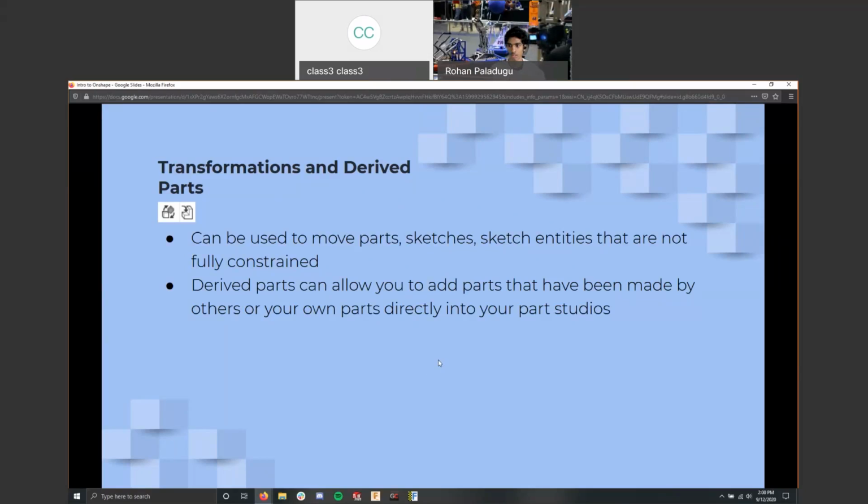Some teams, like ours, tend to just do the math based on our calculations, and then in the assembly we just place whatever part we need accordingly where it needs to go in the shaft. Then if we need spacers, which is primarily where derived parts come in handy sometimes for some people, we would use the measure tool in Onshape just to get that value, and then go into our part studio and create that spacer. But anyways, let's do a more formal explanation of this.